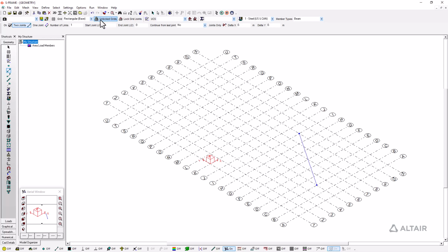So I'm just going to unlock these grid lines. And all I need to do is just left click on one of the grid lines. And if I left click and drag, we get this grid coordinate that appears and basically shows me wherever this grid line is being moved to. So originally it was a nice even 1 meter spacing. Now I'm moving it a little further, 4.4 meters. I can always click the undo button to move it back.